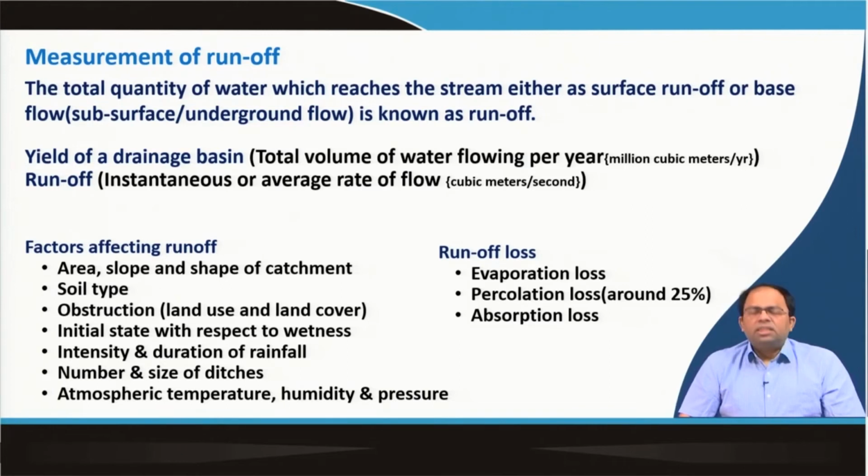And the other is intensity and duration of rainfall. If the intensity of rainfall is pretty high and the duration is low, then immediately you see most of the water goes off as runoff. But if the intensity is low and it goes on for a longer period, maybe more water percolates or infiltrates inside the ground.